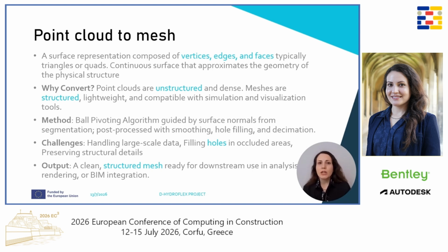For reconstruction, we use the ball pivoting algorithm, and we use the surface normals from the segmentation step to guide the process. Then we smooth the mesh. Next, we fill small holes. And after that, we simplify the mesh using decimation.